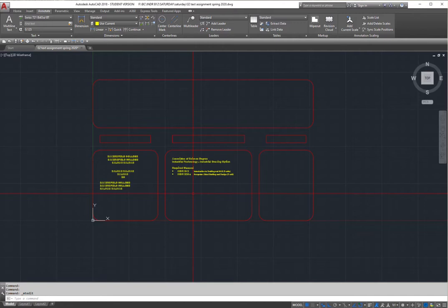What happens is that your program works best when it's inside those limits. So if you know you're going to be working with 8.5 by 11 or 11 by 17 or whatever the paper size, or if you have something different as you progress creating drawings that will require a particular scale, then you will need a larger piece of paper. Then you set your limits accordingly.